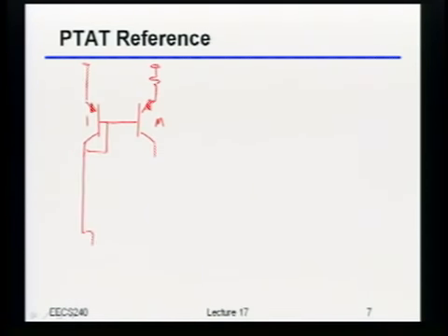Okay, and then just because I don't want this whole thing to actually depend on the supply voltage, I'm going to again play my self-biasing trick. In other words, I'm going to use the current that's flowing through that circuit to basically rebias the other side of the circuit. So you can kind of see like this whole thing just looks like a loop, right? So whatever the current is here gets mirrored to there. Whatever the current is there gets mirrored back to the same spot. So the idea, of course, being that the currents in these two should be then the same.